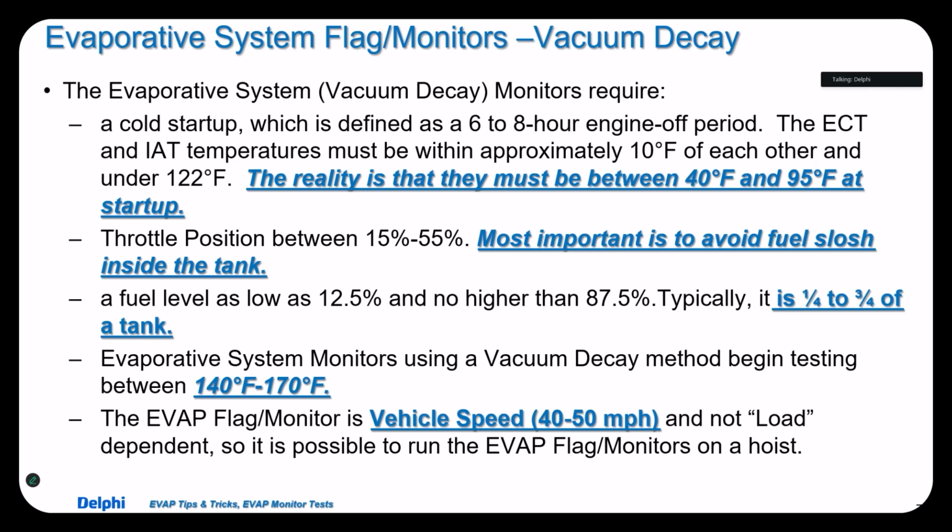We use the engine vacuum. Even a couple of systems that have a key off system, they still use vacuum decay. Pump systems typically do not. They run their full checks through that and verify that the purge is working and the pump doesn't have a small leak. And if it doesn't have a small leak, it doesn't have a large leak.